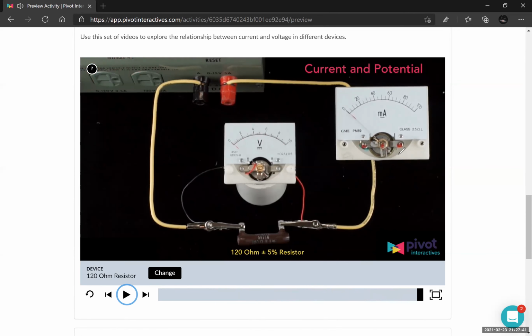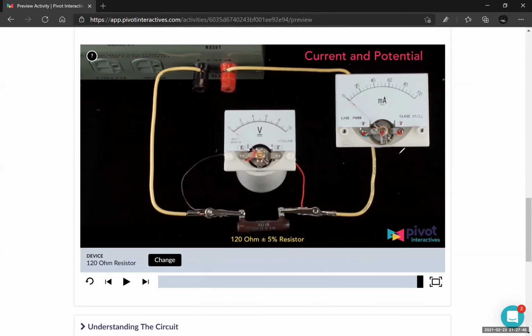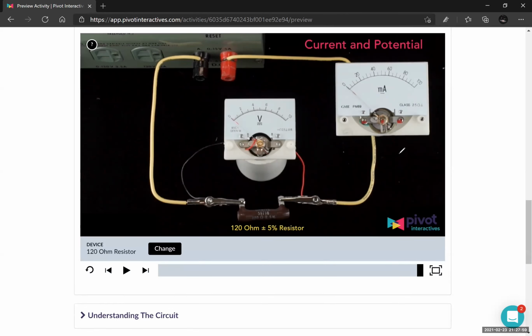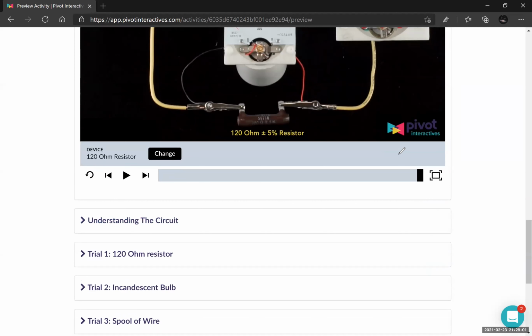All right, so your experimental measurements will be looking at the voltage at some instant of time, and then measuring the current. Now we can see that we go from 0 to 10. It's probably a good idea to have 10 measurements, where each measurement is a 1 volt increment. That means when the voltage is 0, what is the current? When voltage is 1, what is the current? When voltage is 2, what is the current? And so on. That gives you basically 10 measurements.